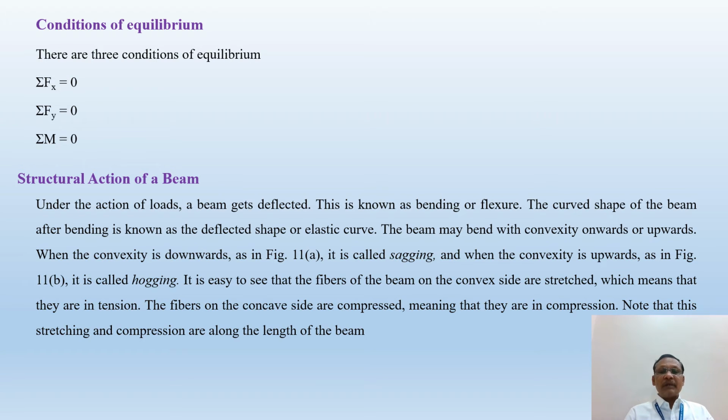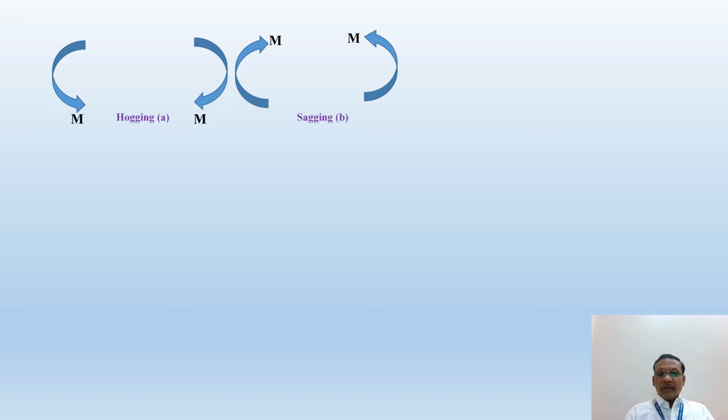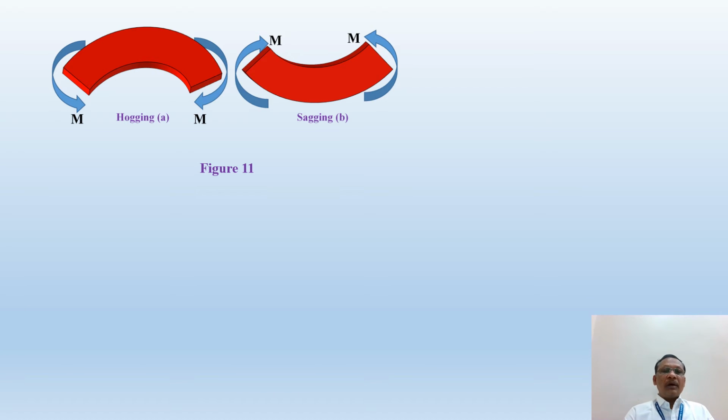While you are calculating the shear force and bending moment diagram, some sign conventions are there. So first of all, if a beam is supported by two supports and it is subjected to vertically downward load, we have discussed the shear force and bending moment diagram, correct? The moment which is acting on the beam in hogging is considered negative and sagging is considered positive.